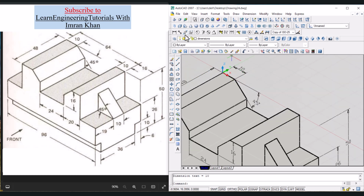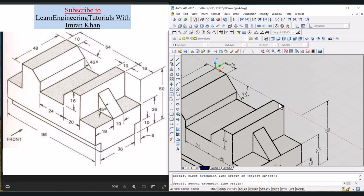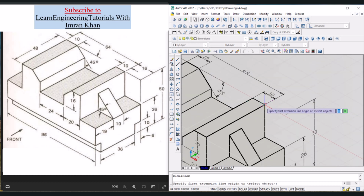Similarly press enter again, select the same corner, zoom out, select this corner, bring the cursor outside and click, press enter again, click on this corner, move the cursor outside and click. We can just move this a little bit further, press enter, click on this endpoint and click on this perpendicular intersection, click, bring the cursor outside and click.